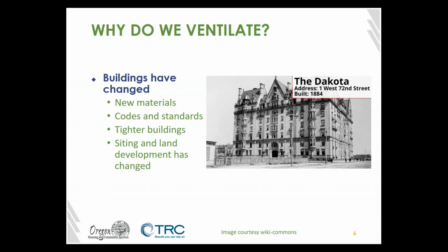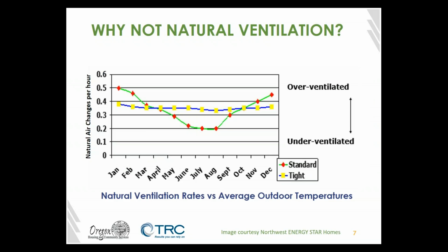So let's talk a little bit about why not natural ventilation. It's because natural ventilation isn't doing it constantly. There's seasonal differences, there's diurnal differences within a day, and then there's hour to hour. Natural ventilation works because there's a pressure difference somewhere in the building, on the shell of the building to the inside, that's moving air in and out, and therefore pushing out the dirty air, the toxin-filled air, and pulling in the fresh air. And that works well and good in some situations, but when the wind stops blowing or those pressure dynamics stifle, then you lose natural ventilation.